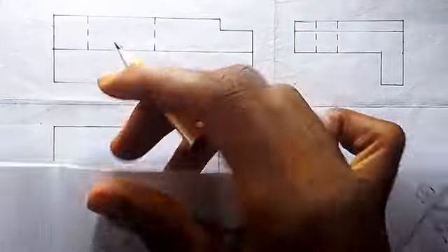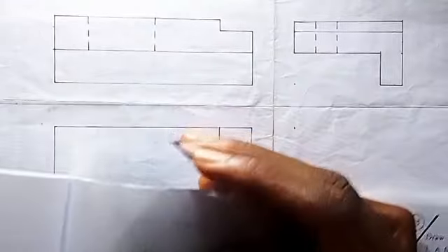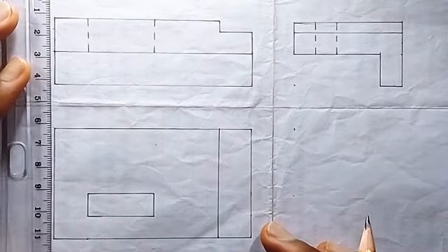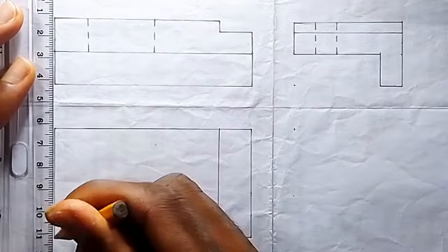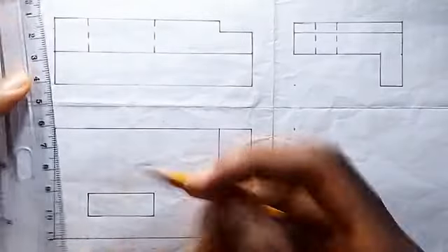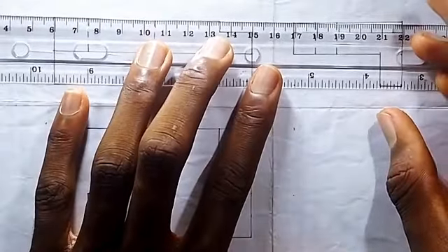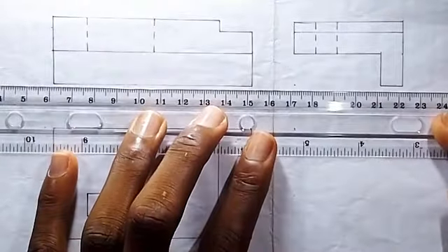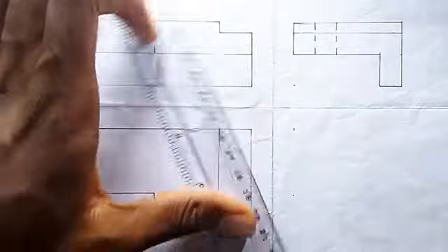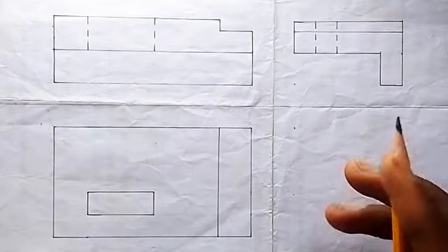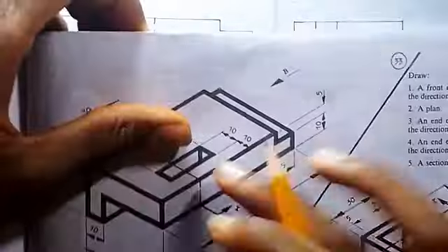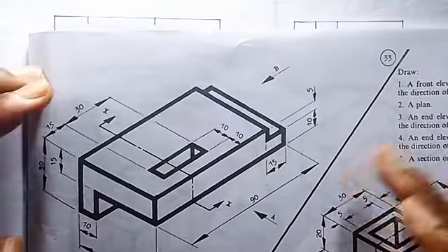The plan, this rectangle, is what we can see here. So to show that our work is correct, we can see how corresponding the lines are. This one is not far, it is aligned. Same with the top, also aligned, and the bottom too, also aligned. So showing that the work is totally accurate. We have fully drawn our first angle projection of this isometric block. What's next? Dissection. Watch out for that video.